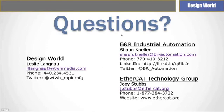The slave devices, because we do things so high speed, you cannot do that in a slave stack. So it requires a hardware ASIC or FPGA to implement the protocol in the slave devices. But those are open for anybody to purchase through multiple sources: Beckhoff, Hilscher, Altera, Xilinx, and now Texas Instruments has their own chips that they've announced, which are attached to ARM processors.